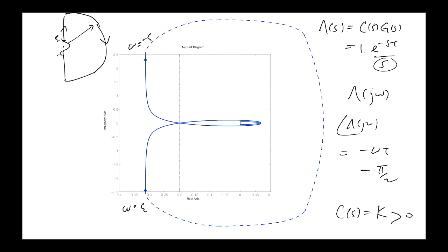All right? And if it moves to the other side of the critical point, it will be inside here. And as we're following this around, coming out the other side, we will end up with encirclements of the critical point when we don't want any. How many encirclements will you get? You'll get 1, 2. And although this looks like it's whizzing around, sometimes it's intersecting the negative axis again and again and again.